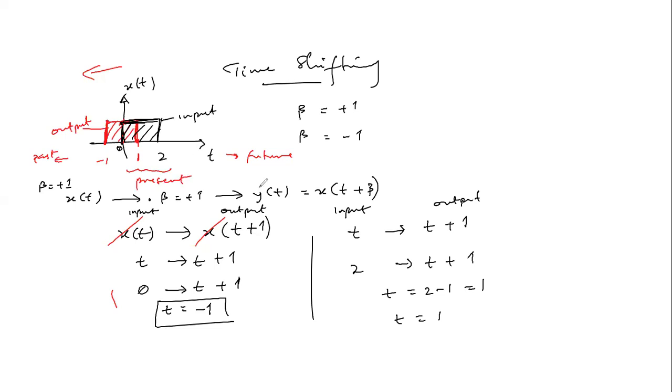So it's either it moves to the future or it moves to the past. But now our signal, which we transmitted in the present, is occurring in the past. Is that realizable in real-time systems? No. But is it realizable in real life? Yes, sir. This is time advance.